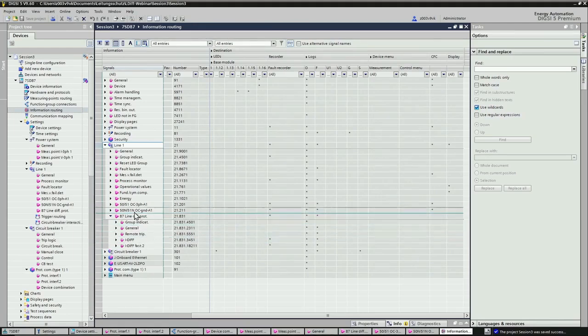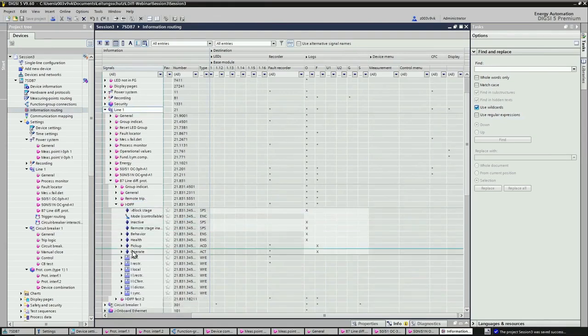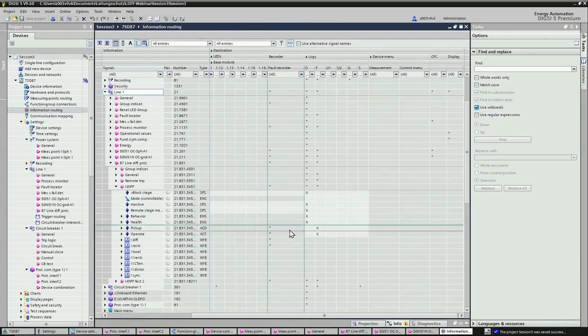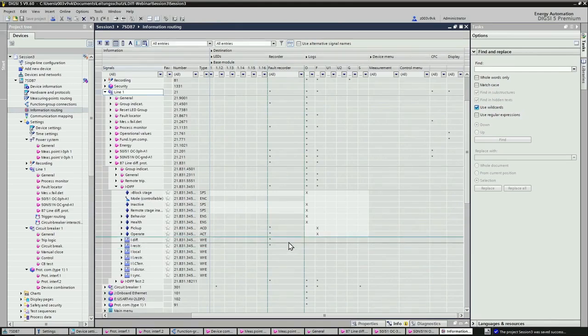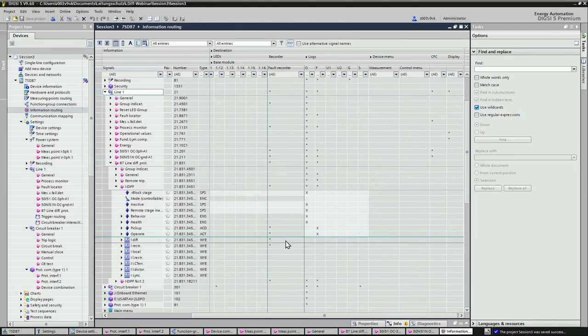And specifically hereby I mean the settings of my IDIF sensitive stage. And here you see the measurements for IDIF and the I restraint values, and they should be assigned to the recorder here. Because later on, when you have a fault in the network and you want to do a fault analysis, this is a lot easier when you have these measurements here.